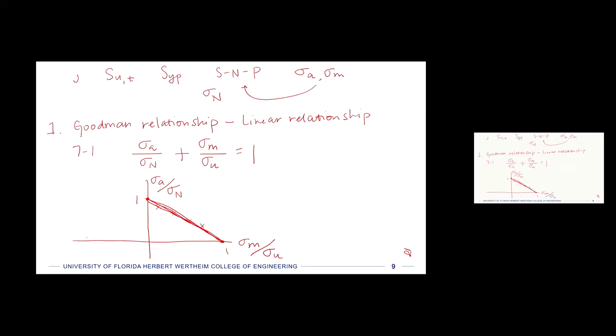And we assume, even though it's not 100% true for compressive, if we drew it symmetric, well, that's mostly symmetric, then that's what it would look like. So this is exactly where this equation comes from. Just drawing a line between those 2 points, normalizing them. So anywhere in the middle there, they have to add up to 1 because it's just a ratio of those 2. So inside is the safe zone. Outside is the unsafe zone.